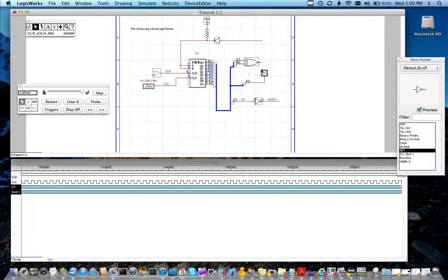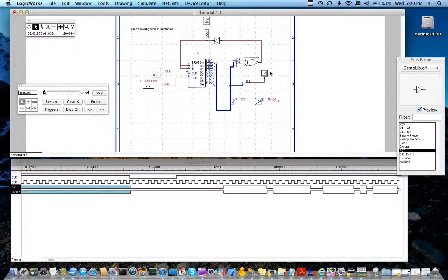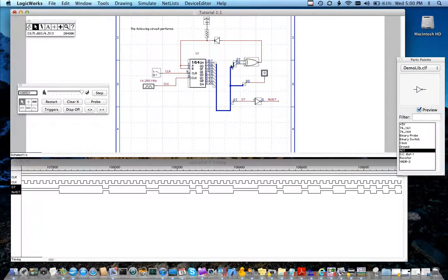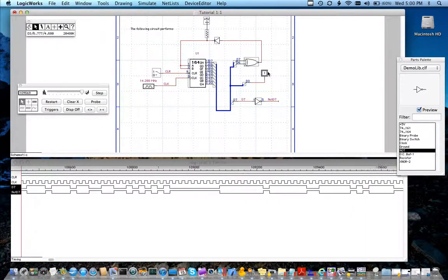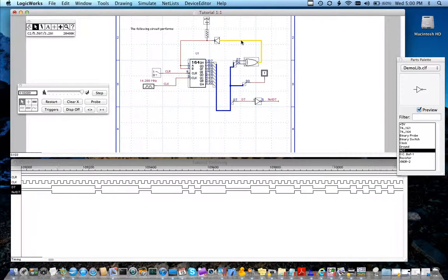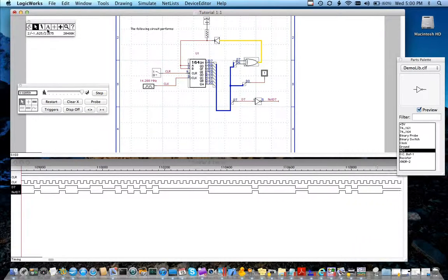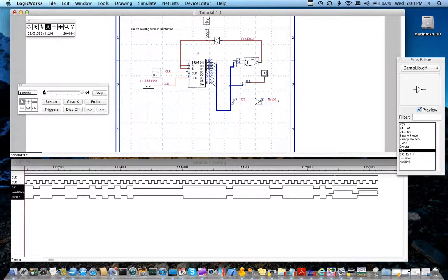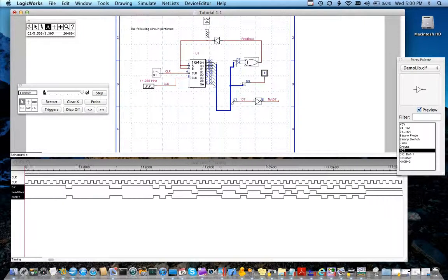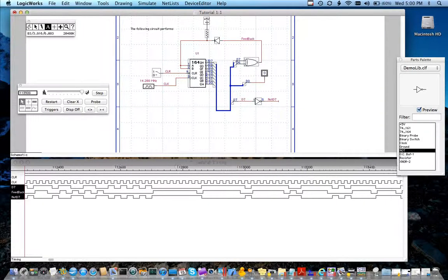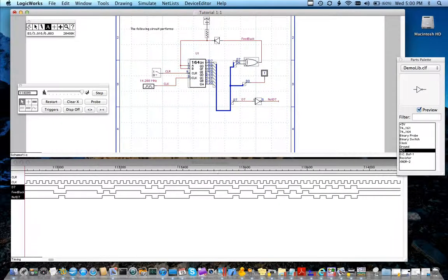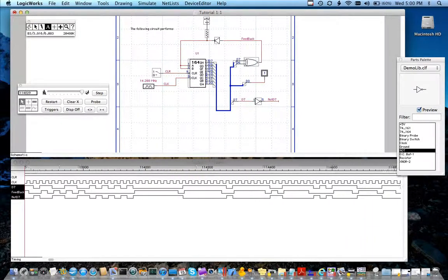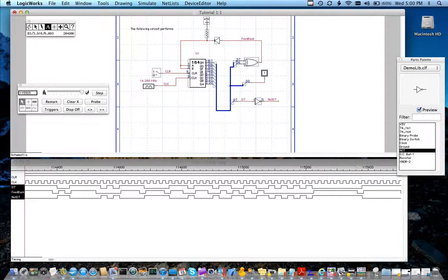Okay, before the circuit will work again, we have to connect this back up and maybe toggle the clear. And you will see that the signal propagates through the bus, and we're getting values out on the probe as we did before. And also, if we rename the feedback, this is called feedback, we should get some values on the feedback. And if we take a look at D7 and not D7, you'll see that they're inverse of each other. So everything's back to working, and that's busing. It comes in really handy.